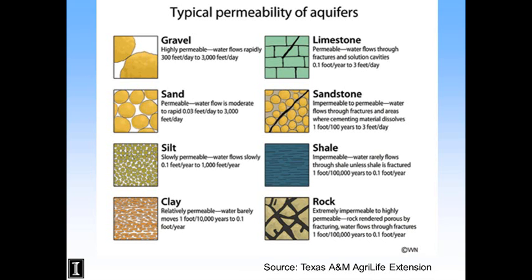In the glaciated part of Illinois, there are areas where there are 2 or 3 different sand and gravel aquifers that were deposited as a result of glaciation. And I know in the majority of the country that's not the case. You're on bedrock aquifers because there's not much other material. Other types of unconsolidated deposits, loess and windblown sand, can also provide water for wells. But permeability is basically a measure of how easily water can flow through that material.